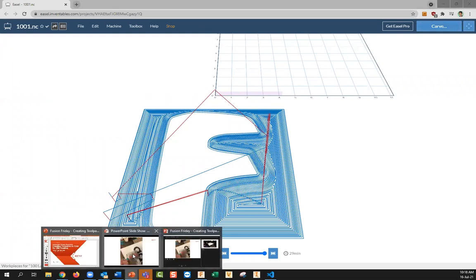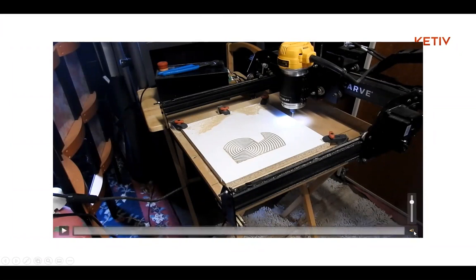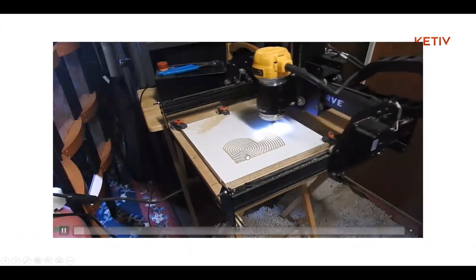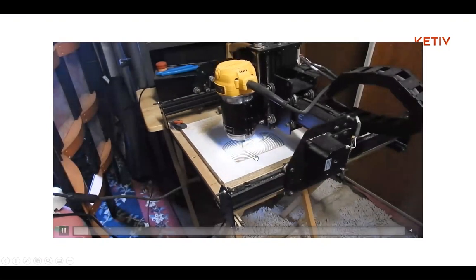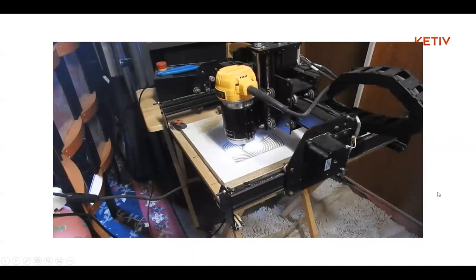And I will go ahead and now show. So I ended up using the 1/8 inch end mill. And let me see if this is muted, because it's going to be loud. There you go. So I ended up using a 1/8 inch end mill, but I actually typed in a 1/4 inch. That's why it had these spirals. So I had to stop that. But now I changed the toolpaths to run an 1/8 inch. So now it's going to cut as expected.